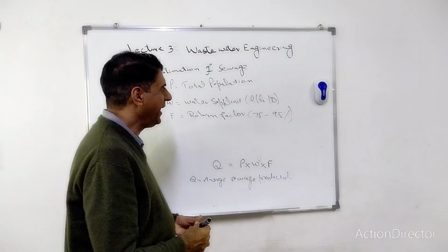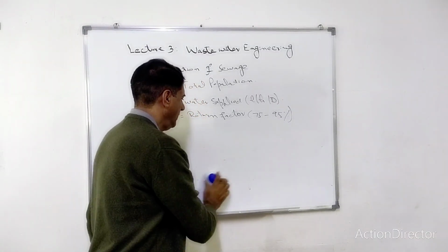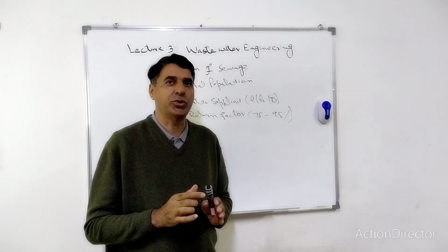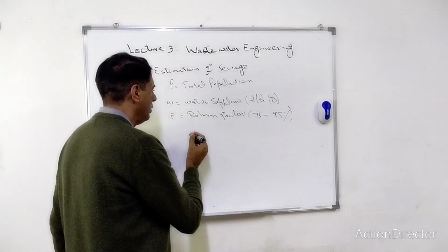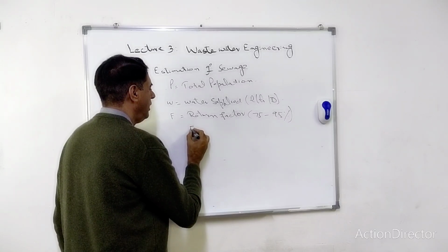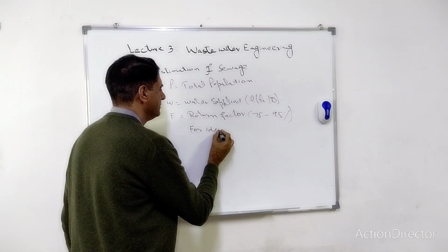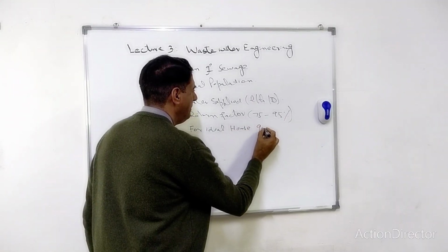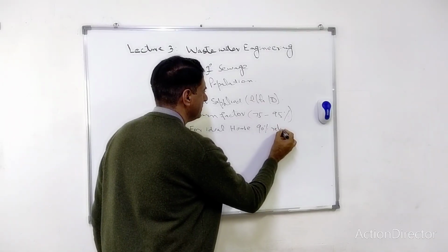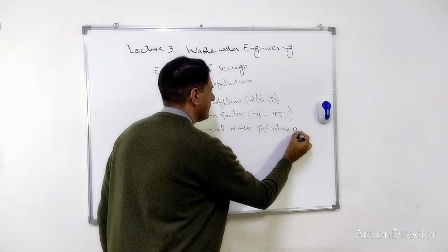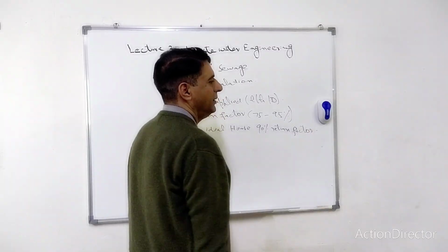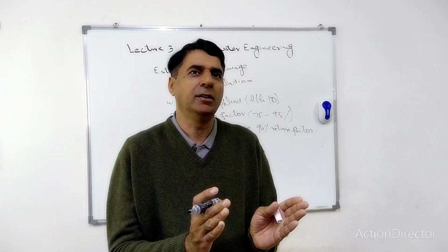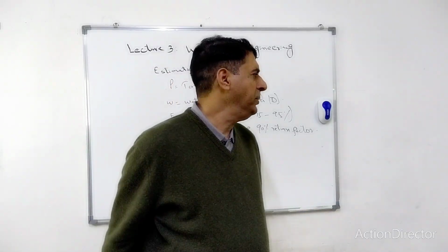And second thing I would like to tell you, when water is being supplied to any house, for an ideal house, which means well designed, 90% is the return factor. You can ask this question, why not 100? Now I will give you the answer, where the other 10% goes.